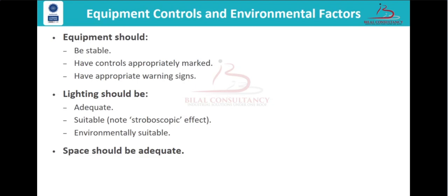Moving forward towards the markings of work equipment, all work equipment has to be marked in a clearly visible manner, giving any relevant health and safety information such as stop and start controls, abrasive wheel rotation speeds, safe working loads, color coding of gas cylinders for recognition of contents, contents of storage vessels, and nature of hazardous contents. And lastly, color coding of pipe work.